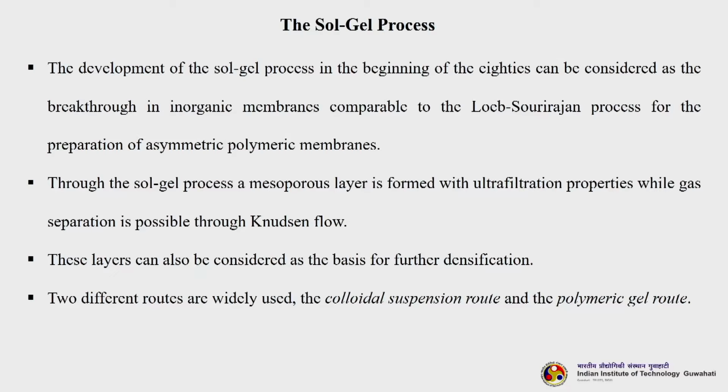initial cost being high. Through the sol gel process, a mesoporous layer is formed with ultrafiltration properties, while gas separation is also possible using Knudsen flow. Now, these layers can also be considered as the basis for further densification. That means, once we get some membrane using our sol gel process, further we can densify it using vapor deposition to achieve certain target oriented separation.